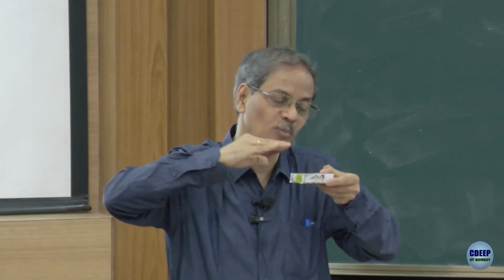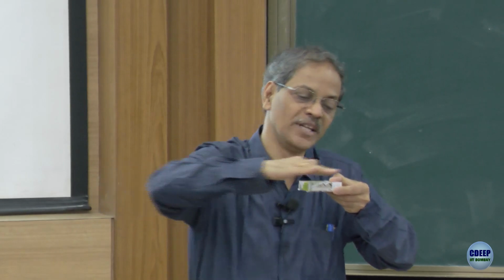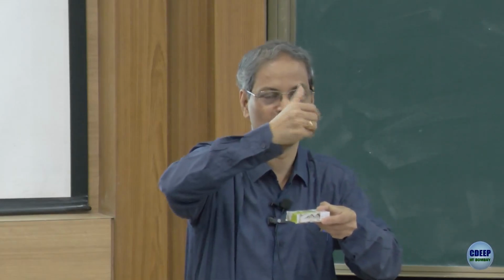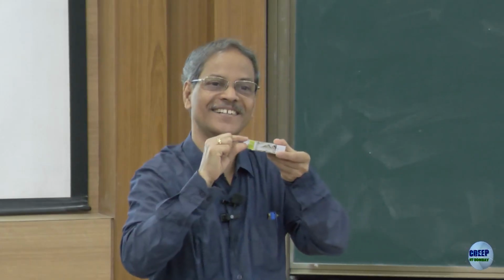So I would assume that the stresses also will be restricted to this plane. Whatever is the stress, normal direction would be 0, because the normal direction stress at the top is 0. It is a free surface. At the bottom it is 0, and it is very thin.